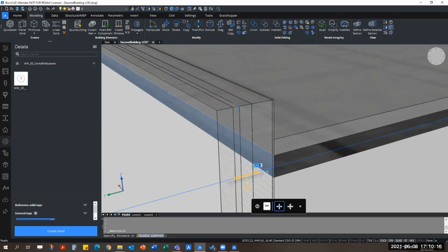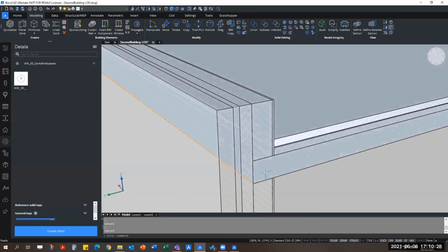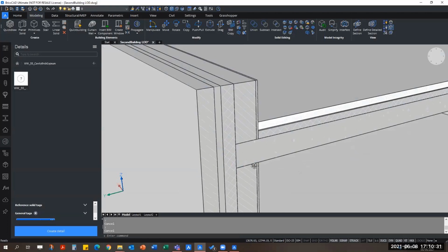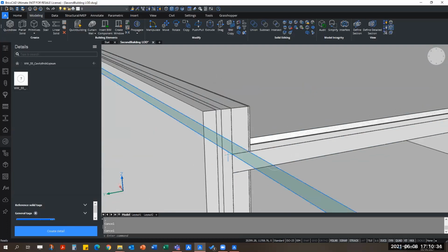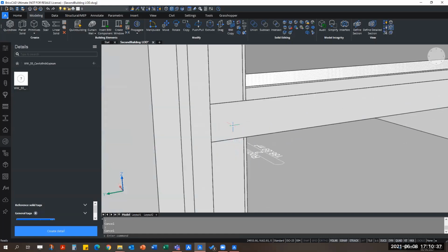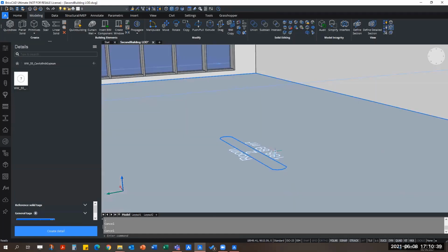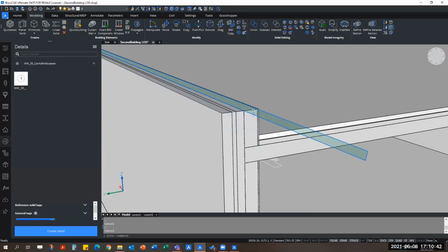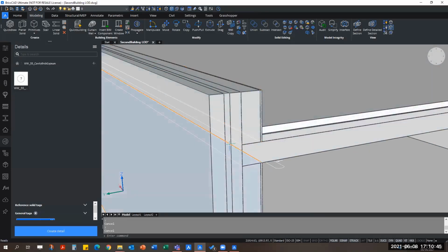You might also realize the snap is not turned on, like in my case. So I always do an F3. And what I do want here is I want this slab to carry on all the way to my installation layer. So I have my block work sitting under my concrete slab, and then again another block work to continue right at the same height. So I have on this plane a thermally broken junction where it's being protected by the insulation. But we'll have a little kind of play.